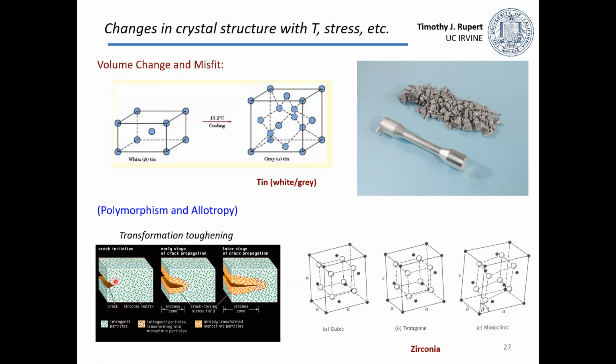When you pull on this type of structure, this little crack acts as a stress concentration. So there's really high stresses around that notch. And what you would find is if you went and inspected the materials, you would find that most of this is tetragonal. But if you zoom in, you would get monoclinic particles close to that crack tip. So that tells you that the stress is actually changing the crystal structure near that crack.